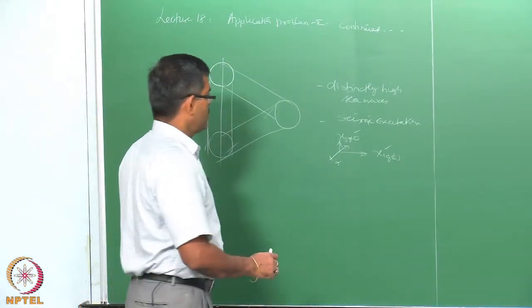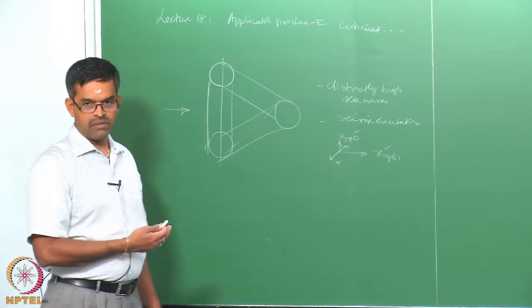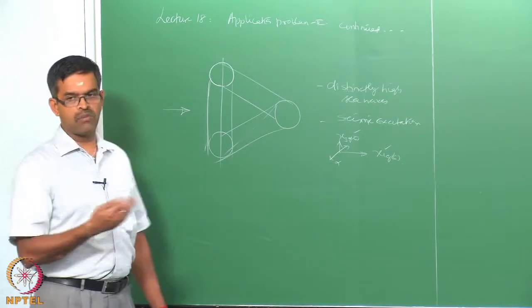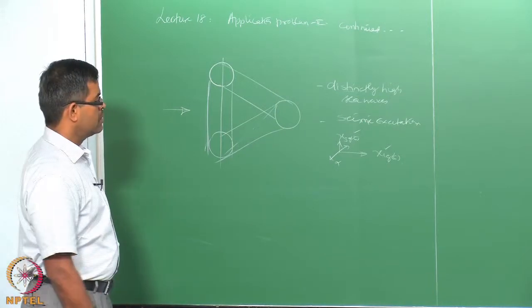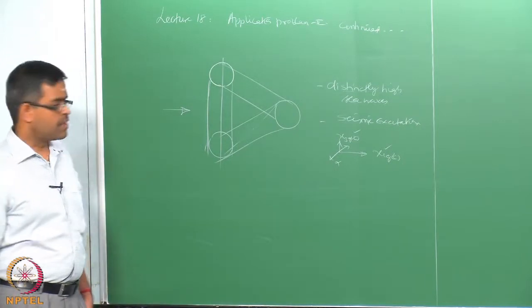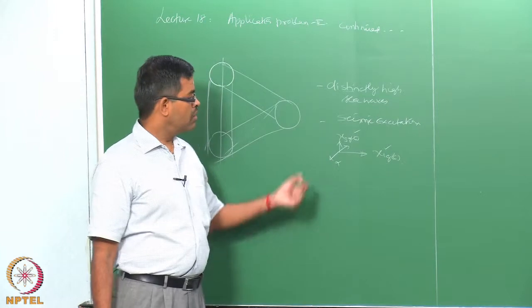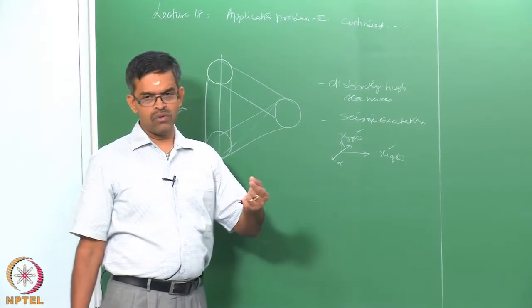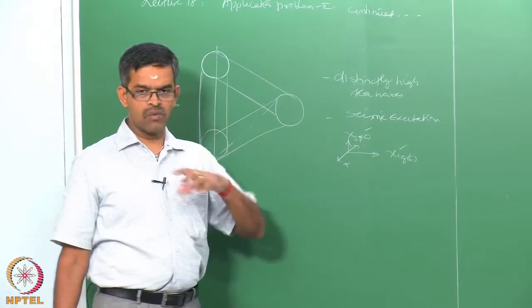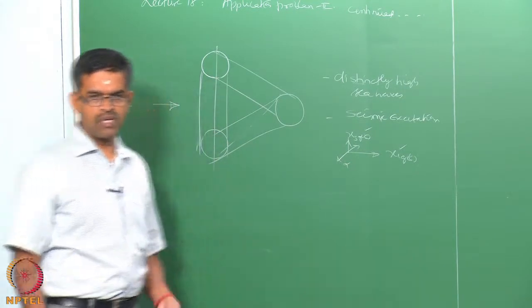Now, it requires a random time history for the ground motion. The ground motion needs to be simulated, because earthquakes occurring at the seabed are not actually measured. Therefore, one needs to simulate a seismic signal closely related to the sea quake or earthquake in the region where the TLP is located. I will come to that slightly later.